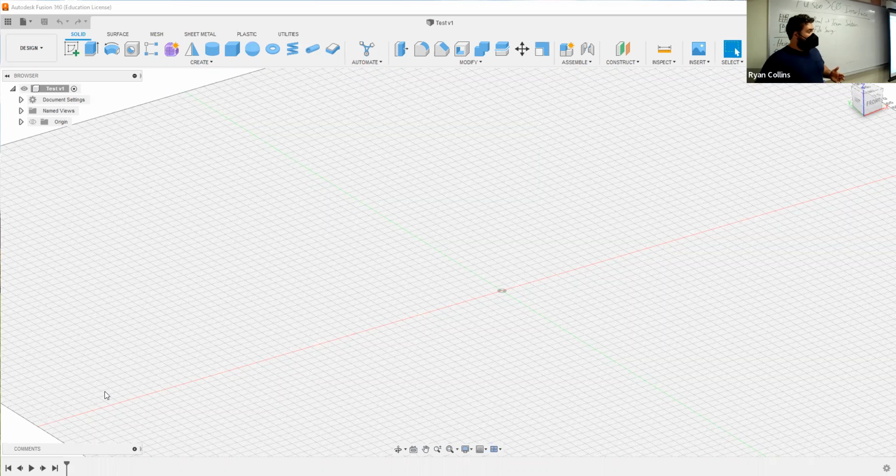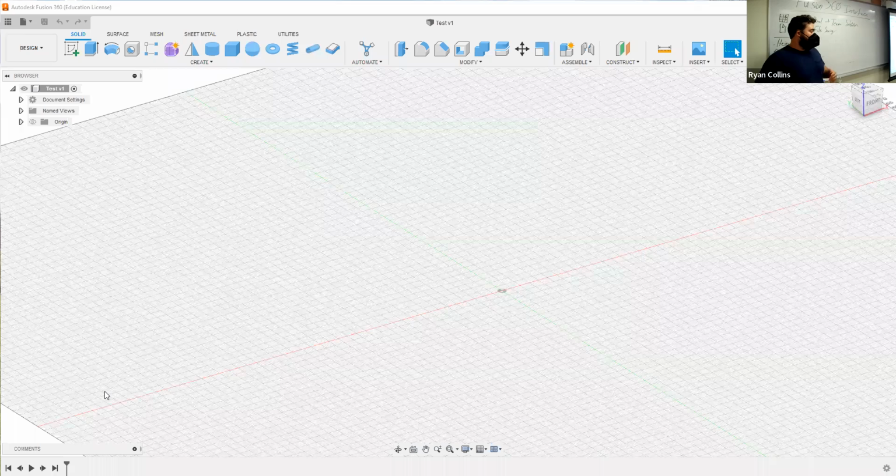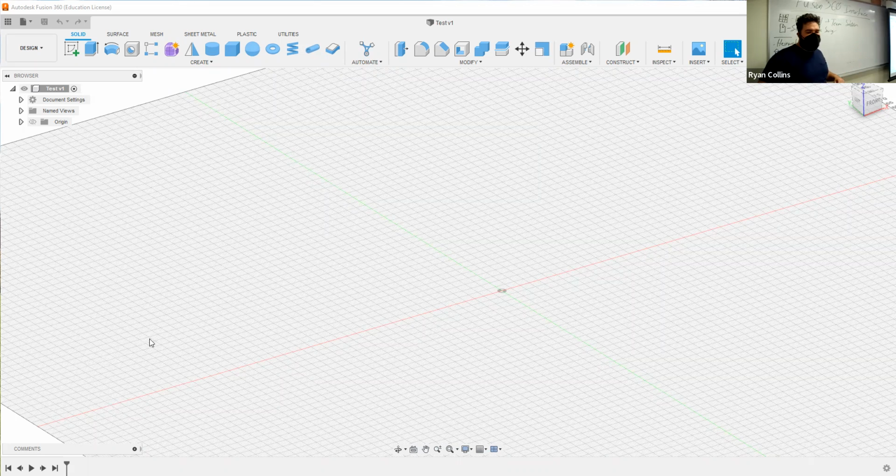So say I wanted to put a curve on this thing that I just built. I rounded out the edges. Great, but I found out later that I really needed to add a hole near the corner, and that rounded-over thing is messing with me. Well, what you do is move the time slider back before you put that curve, then add the hole, snap back to current, and it'll recalculate all the stuff you've added. If there are issues, you have to correct them, but you can drop actions in between actions. So it's really convenient.